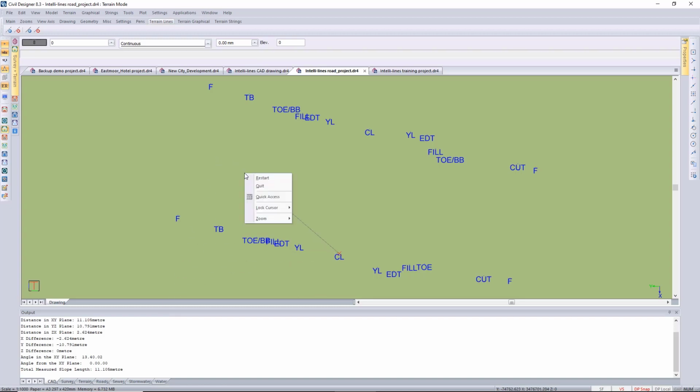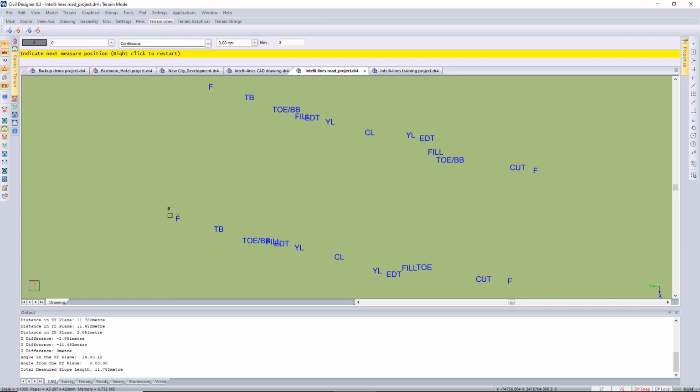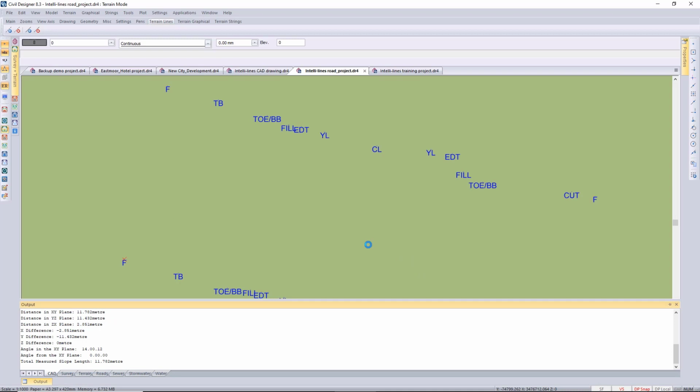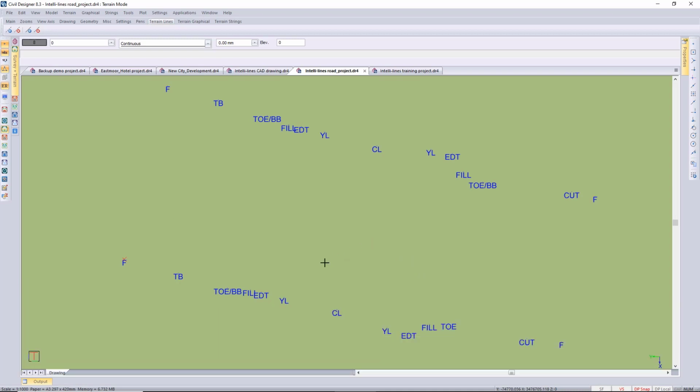I can maybe do from fence point to fence point. So also under 12 meters. So I'm going to use a maximum line length or search distance of about 15 meters when it needs to join from one point to the next closest specifically named point.